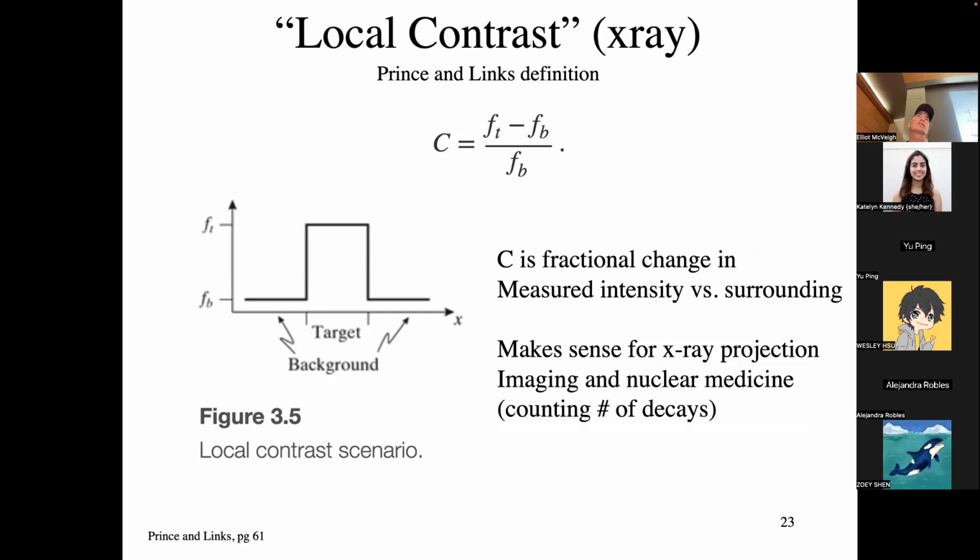The sampling, okay, so the question is, a couple of things came up. One was the Nyquist criteria, one was aliasing. When you basically have objects that are higher frequency than your imaging system can image, they will look like they're lower frequency objects because they start combining together. And the final question was, if you have more detectors, i.e. higher spatial frequency of detectors, yes, it's a higher sampling rate, right? And so what we'll do eventually in CT is we'll look at the sampling rate required to make a good picture in 2D. Like for my detector array, how many views are required to make a good sampling? Okay, we'll get there.